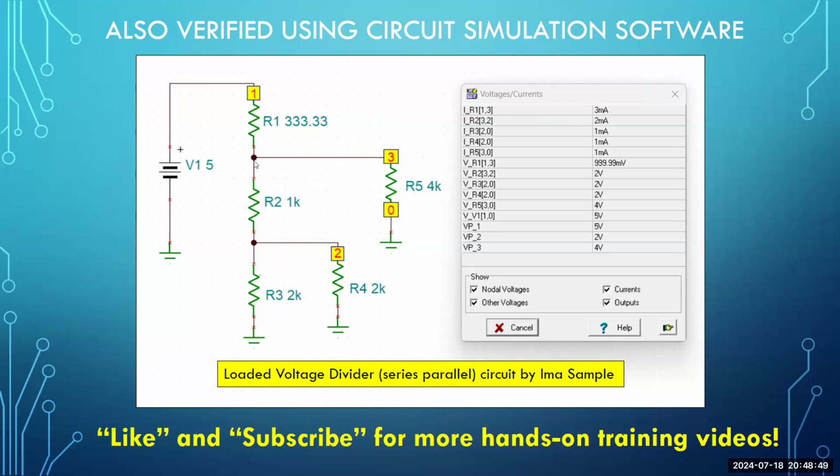And finally, at node B, which sits between R1 and R2, we needed to supply R5 with 4 volts, 1 milliamp. That allowed us to calculate the 4K ohms. So if I have 1 milliamp flowing up through R5 into node B, and I have 2 milliamps coming up through R2 into node B, 1 milliamp in, 2 milliamps coming in, how much current must be exiting through R1? So 1 milliamp plus 2 milliamps we determined was 3 milliamps. We calculated it. We measured it.